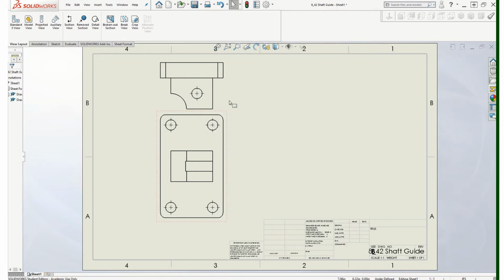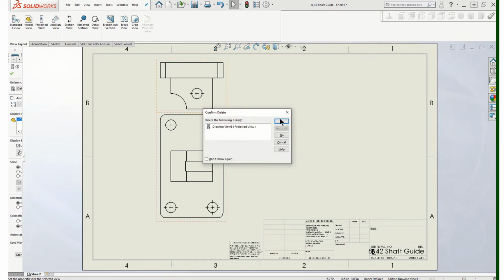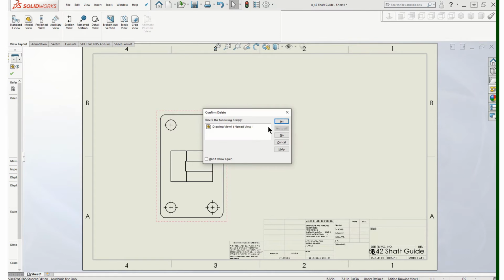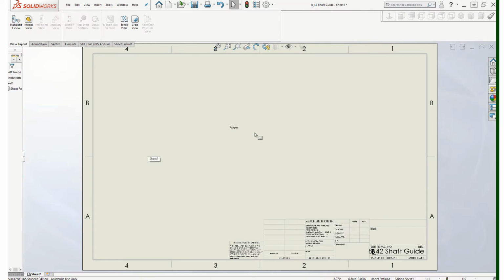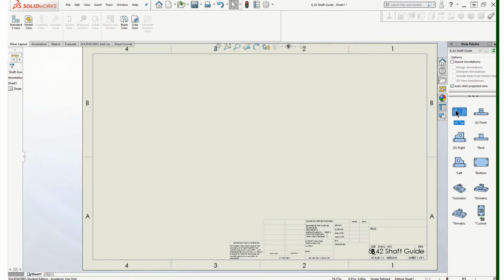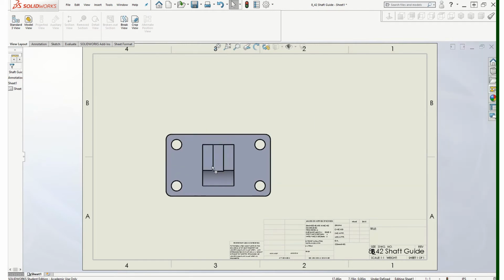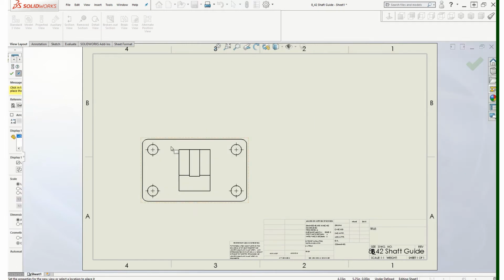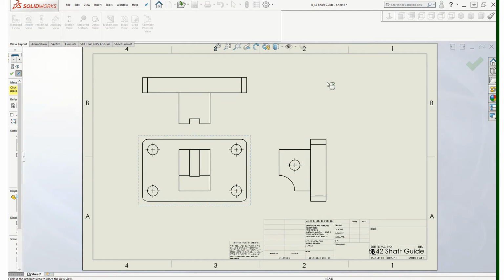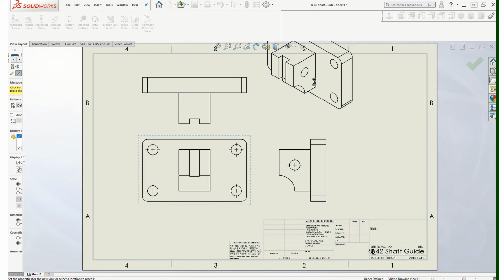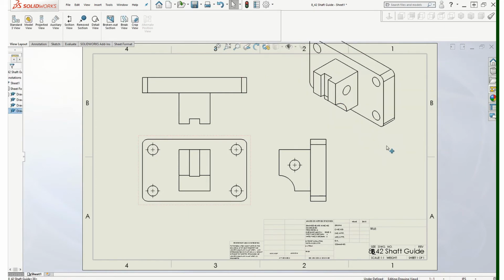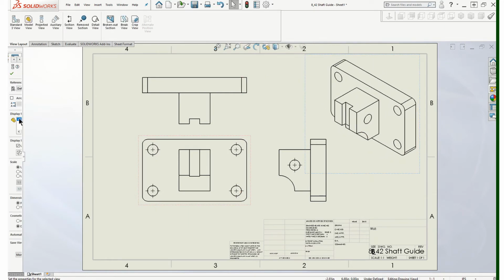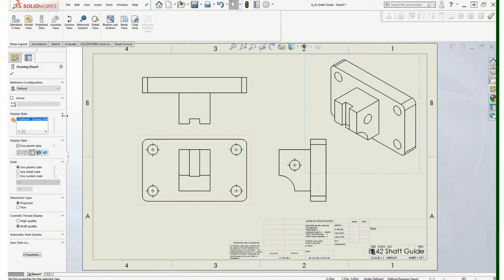Again, the front view shows the most information, fewest hidden lines, and the longest dimension, but that longest dimension is going to be horizontal on the page. So again, this is a much better front view. Now, let's put all these on there. Now, these are fine. Now, this scale is a little big. I can bump that scale down.